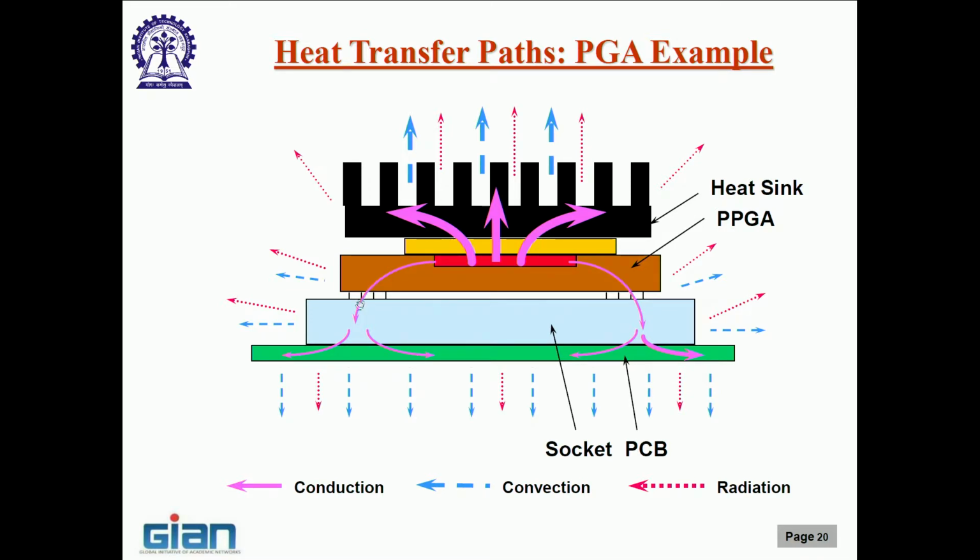Okay. So, conduction through all these layers into the motherboard and from the motherboard into the ambient again. Now, you can readily appreciate the fact that this thermal resistance is going to be much higher compared to something through a copper, then to a heat sink, which will typically be aluminum or copper, versus something that goes through this substrate, then maybe an organic substrate into the motherboard, then through these pins into the socket, then into the motherboard. The thermal resistance is going to be much higher.